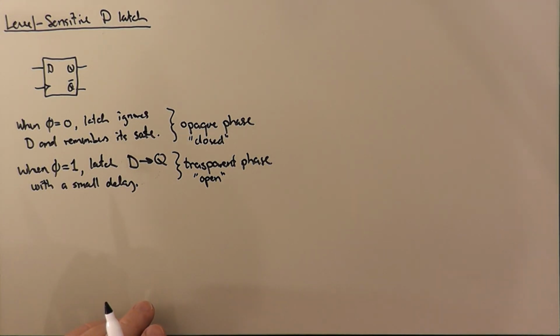And this type of latch is what we talked about last time down at the transistor level. You can build one of these things with a pair of cross-coupled NOR gates and add on a clock device in series with R and S, and then you basically feed D and its complement into S and R, and you get this structure.